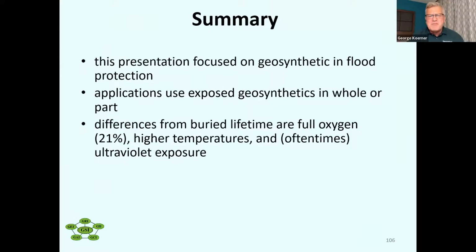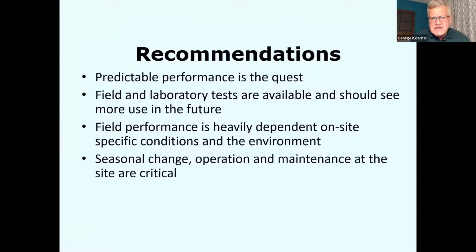As far as a summary of this presentation, it certainly has focused on flood protection. The applications are exposed geosynthetics in whole or in part, and this will provide challenges in regards to the formulation of these materials. It's a very different lifetime of a material based on full oxygen exposure of 21%, high temperatures, and also UV.